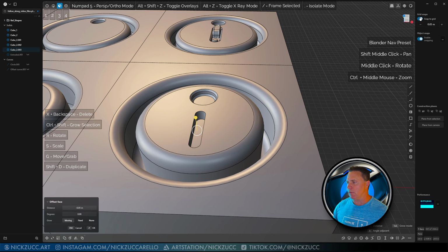The other thing that I could have done, I'm going to hit undo for this. If I select the whole entire curve, tap 2, select this. Instead of join curve, you remember join curve was J, and if we hit Alt J, it will unjoin the curve into all these different parts and pieces that makes up the totality of this curve. So sometimes you're going to need that for your curves. You're going to need to unjoin things to build parts and pieces, right? Okay, so I've got this here.